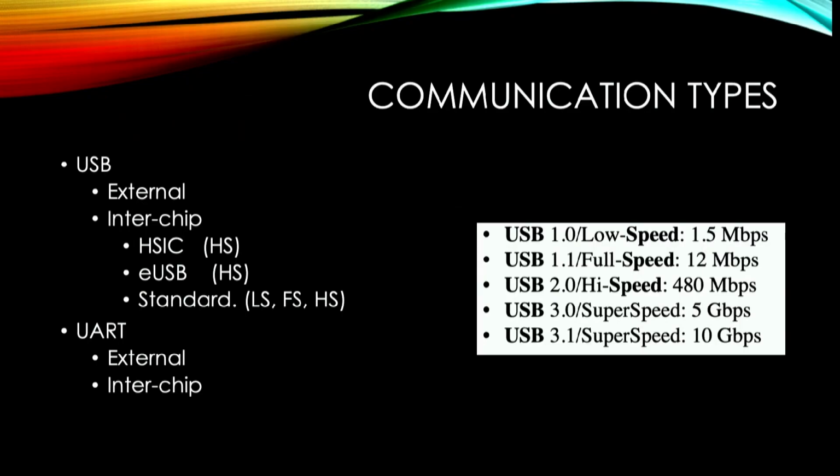Also, one thing to think about: USB interchip could easily be a substandard. So high-speed interchip will be a substandard of 2.0. When USB comes up, it queries how many devices are out there, because you can have multiple devices on USB 2.0. But we're looking at an embedded device, so you will not have multiple devices on USB. Sometimes that functionality will not even be executed, because it already knows the identifier is 1, since there's only one device on the bus.